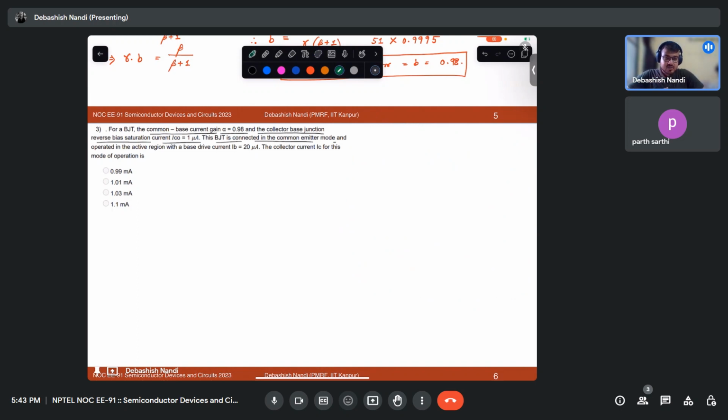Okay, I'll just cross check and tell you, because I was under the impression that due to the shorter range of the base, you can accommodate that recombination. That will go into the next step. So anyway, you can assume this configuration in such a way that if it is your PNP transistor, and this is your emitter, base and collector, you want the emitter base junction to be forward biased, and your collector base junction to be reverse biased.